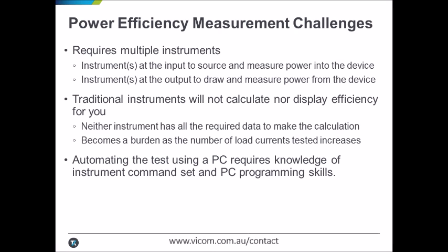For calculating efficiency at a single low current, this is not a big deal because the calculation is simple. However, device characterization requires measuring efficiency at multiple low currents, and this manual calculation quickly becomes burdensome, not to mention a potential source of error.